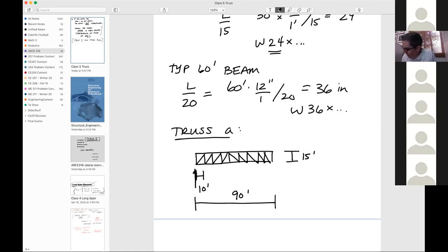Over here, we've got a reaction. At both ends, we've got a reaction. So I'm just going to call that R1 and R2. And so on the truss, because there's more than 4 point loads, we can smear it. And so this is what we had calculated earlier. That would be the 10.5 kips per lineal foot.